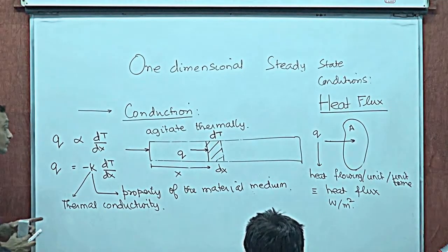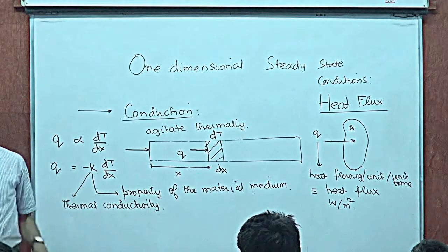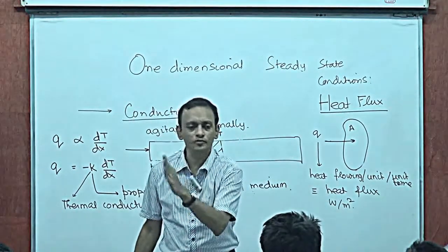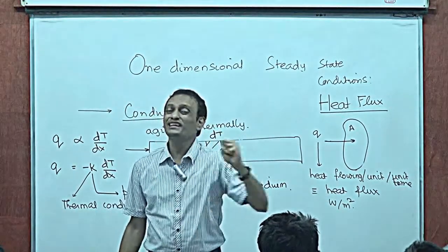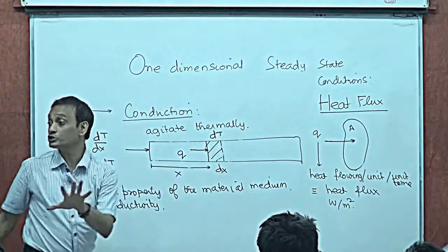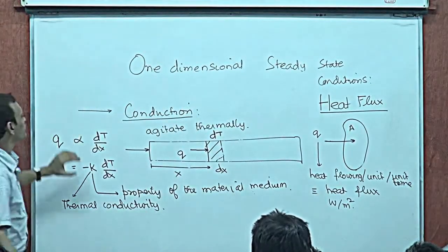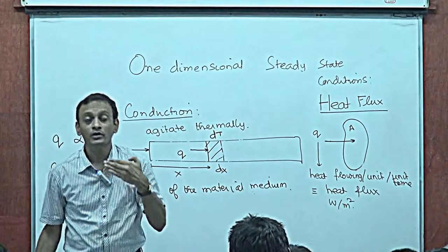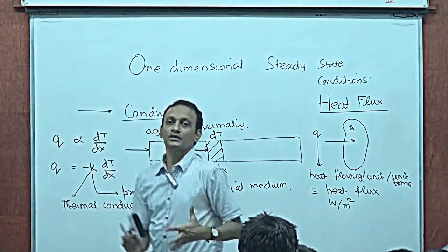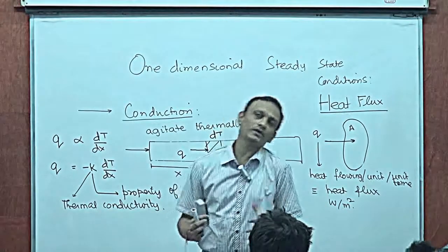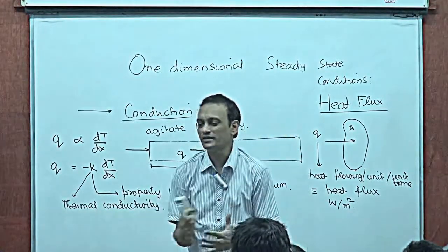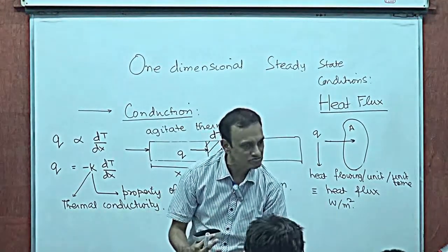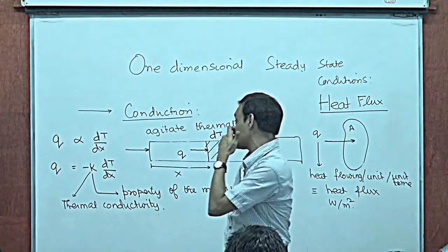Now, as far as this k is concerned, different cross sections in general would be at different temperatures. K, very realistically speaking, is a function of temperature, but it's a very weak function of temperature. So for all practical purposes, for regular applications, we take K to be temperature independent, almost a constant, independent of conditions like temperature, pressure, etc.